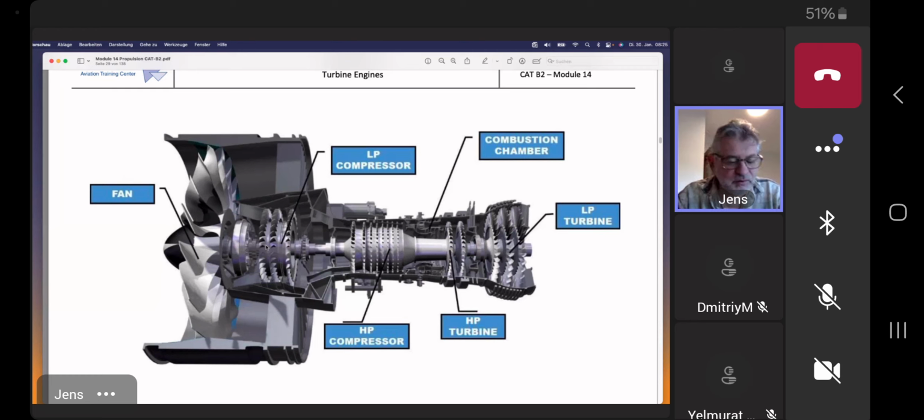You will also remember speed of sound and divergent, convergent, Bernoulli's law. Just keep it in your mind or remember how a fluid, a gas behaves if it's going to be accelerated. We have our two pressures, the dynamic pressure and also the static pressure. And if a fluid enters a divergent shape, what happens? The kinetic energy, the dynamic pressure goes down.